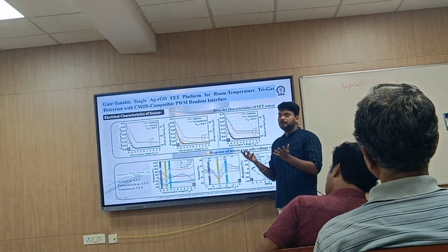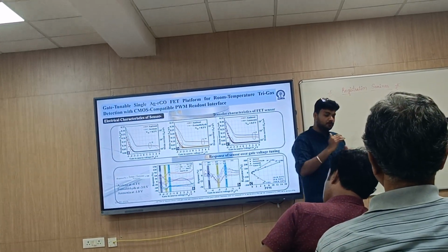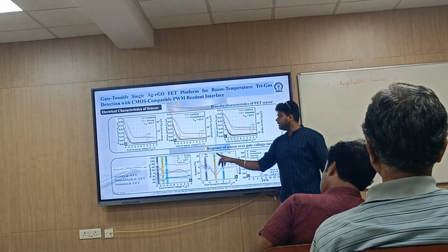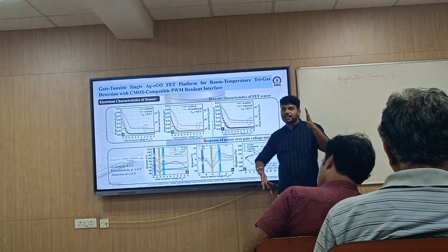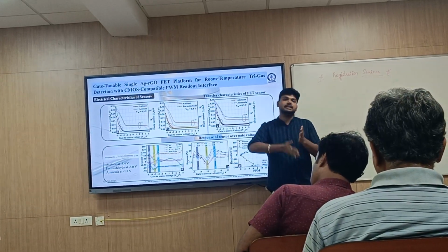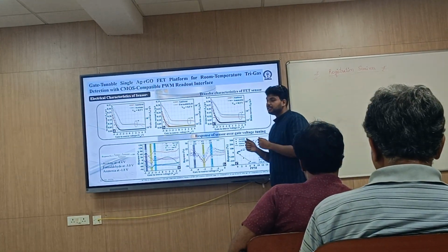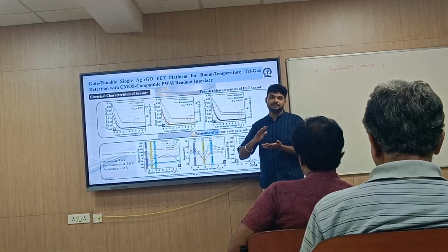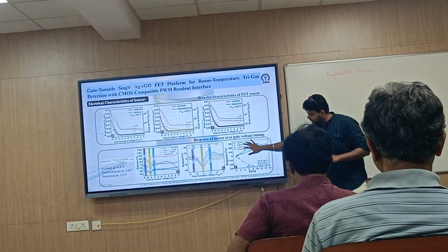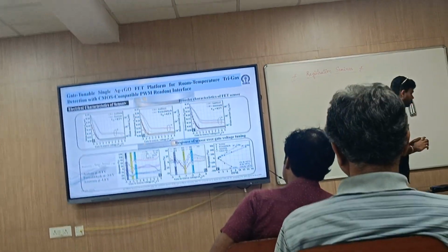Then I changed the proportion, with all three gases present. Here 0 signifies 1 ppm and 1 signifies 2 ppm. I changed the mixture proportion and the response changed up and down analogously. So from that we can check that it's also quantifiable from the amplitude. Then I plotted the amplitude of all three gases and got the LOD and so on. So three gases at a time.